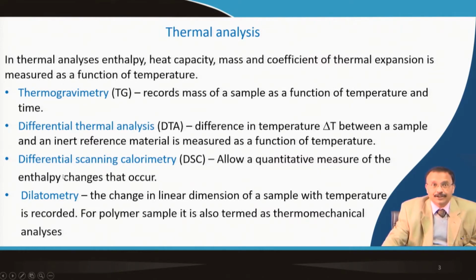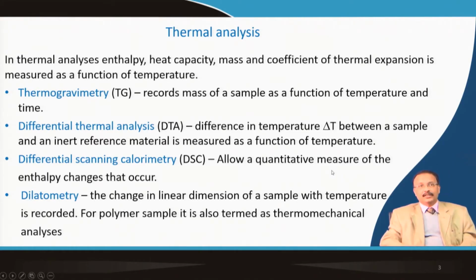Differential scanning calorimetry basically allows a quantitative measure of the enthalpy change that occurs in the sample. In dilatometry, the change in linear dimension of the sample with temperature is recorded. For polymer based samples, this kind of measurement is also termed thermomechanical analysis.